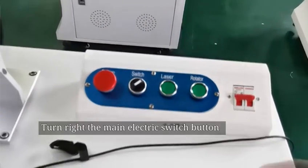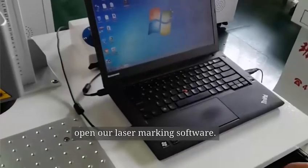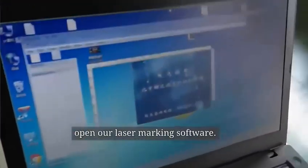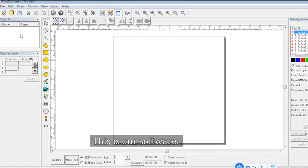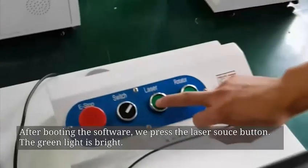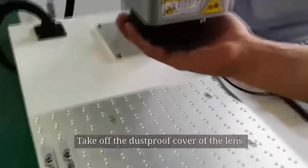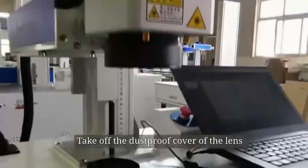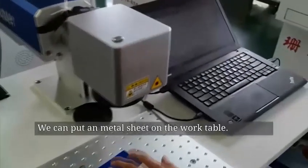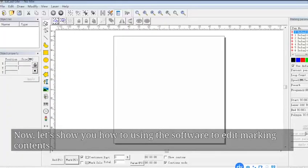Okay, now let's turn on the computer and the laser marking machine. Open our laser marking software. This is our software. After booting the software, we press the laser source button. The green light is bright. If you have connected the rotary, you also need to press the rotary button to make the green light on. Take off the dustproof cover of the lens. We can put a metal sheet on the work table.